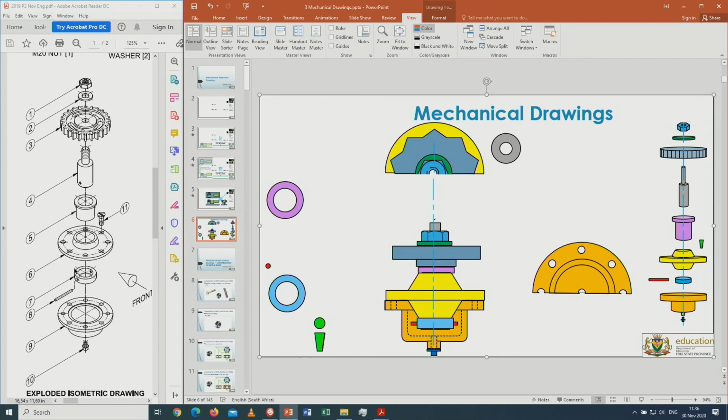Okay, and then there's some screws that have been placed over here. So there's the screw, and since it's going to be sectioned in half, I can turn one screw in over here at that point, and I can turn the other screw in on that side over there, and that might be visible. But since this is a quarter section, I will only see the open end over here, and I won't see this part over here.